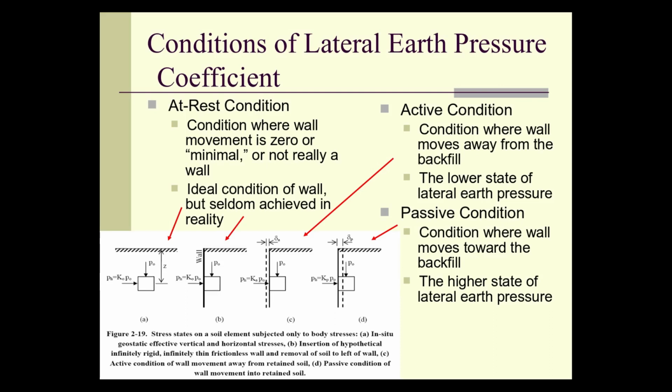An at-rest condition also can take place when you have a rigid wall. Now, a rigid wall is one of those great engineering concepts that really doesn't exist in reality, but we say that. If we have a wall that is very unyielding and doesn't move, sometimes it will do at rest, but not very often.